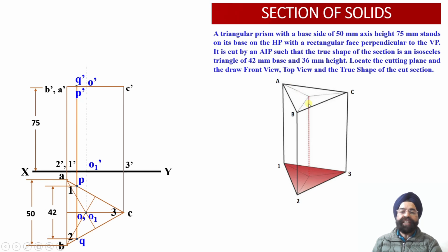The 2 points we have already obtained alongside the adjacent faces over here. Now the third point we have to locate alongside the vertical edge, which will be obtained by intersection of these two adjacent top face edges, which have already been cut by this auxiliary inclined plane.